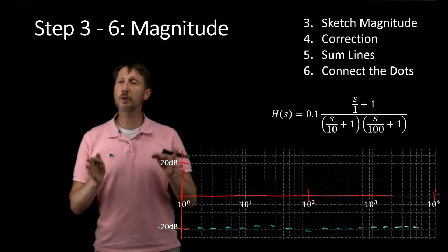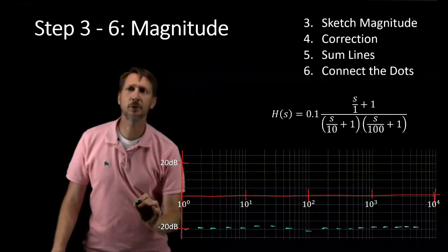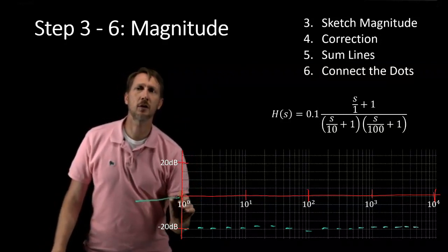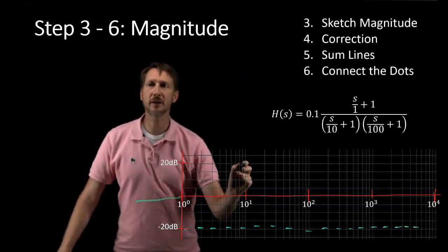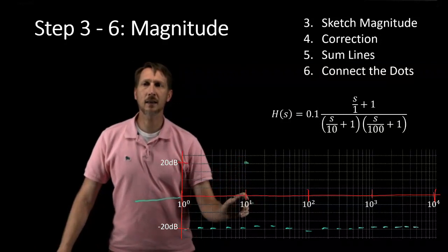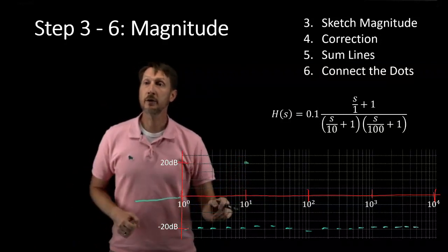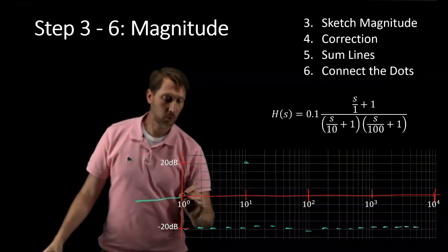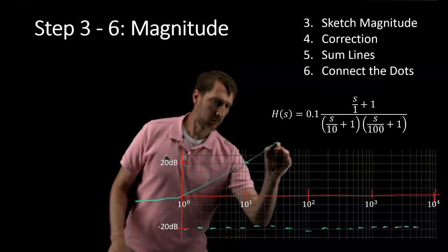This designator, we just put it where it's convenient. So we can expand this plot and we'll just say we're going to go at 0 until we get here. And when we get here, we're going to go up at 20 dBs per decade. So 1 decade later is from 10 to the 0, which is 1, to 10 to the 1, which is 10. And we're going to connect these two lines with a straight line.